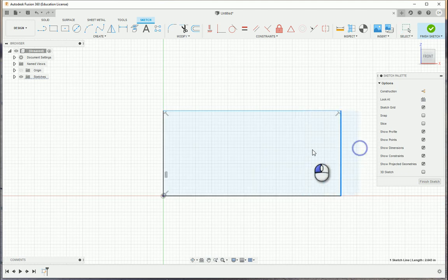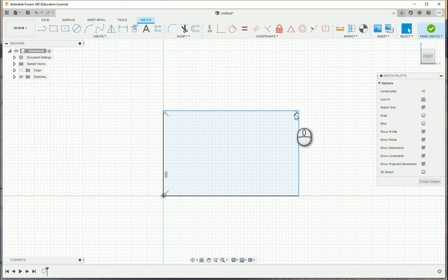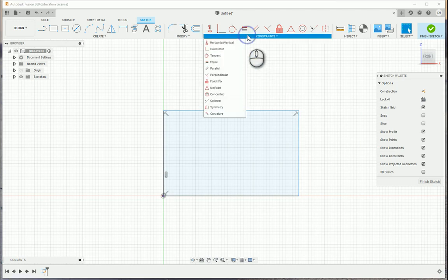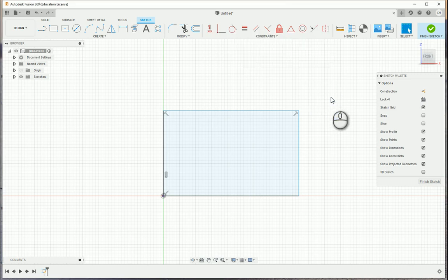And that's the thing we're wanting to look at: what exactly does this mean? You'll see these little icons. This is a perpendicular constraint. Again, that's dealing with your geometric constraints. Those are automatic sketch constraints that are placed in. You'll see this icon over here, which is a vertical constraint. That means that line is vertical with that axis, and it maintains that. We should probably also see a horizontal constraint there as well, but it looks like the perpendicular constraint is also keeping that in place.